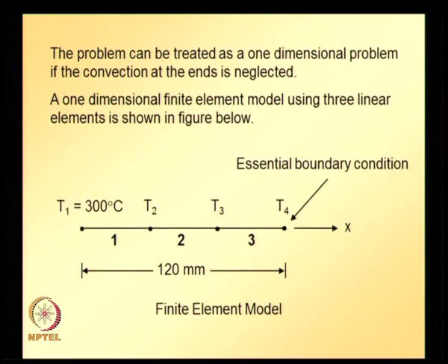Since the material properties like thermal conductivity, convection coefficient, and also since the length of each element is same, element equations are going to be identical for all the 3 elements.